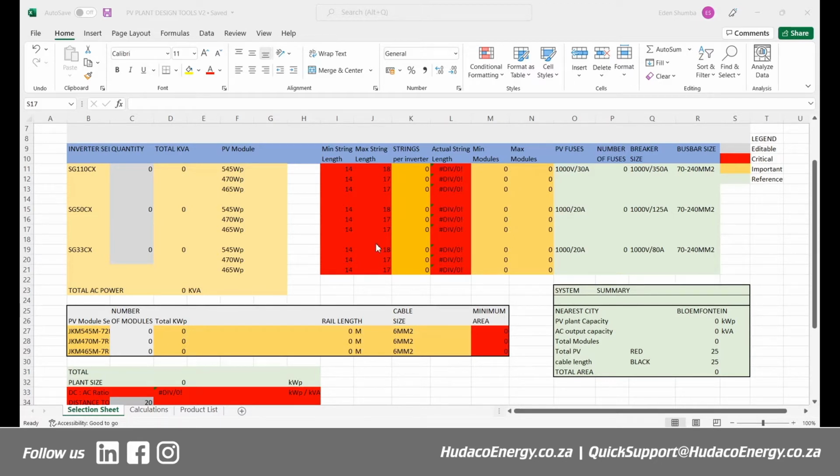And someone would ask, why is it that the 545s can allow you up to 18 per string, while the smaller ones only allow you up to 17? The difference is in the voltage. Remember, normally what determines the string length is the voltage. So the 545 has got a voltage of around 49 point something, and then the 470s and 465s have got a voltage of 52 or 51 point something. So that means their voltage quickly adds up. That is why they can form smaller strings than the 545.